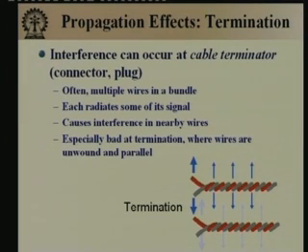First of all, if two cables are running in parallel, what might happen is that the signal in one might affect the signal in the other. So, there is some kind of linkage between the two. This is called crosstalk, that is one thing. This is more pronounced at the termination end, and at the termination end, if you do not terminate the thing properly, if you just leave it like this, then the kind of distortion and the kind of noise that will be introduced will be much more.